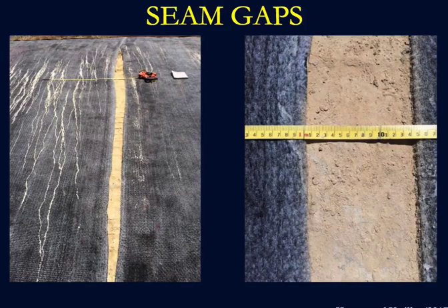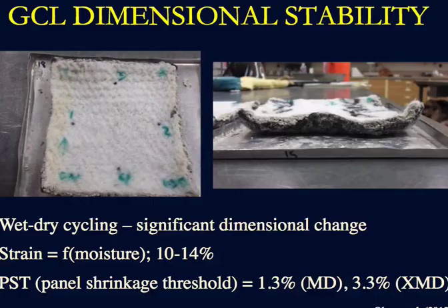And certainly here, the panel shrinkage has overcome that amount. And the close-up image in this case shows a gap width of 150 millimeters or 15 centimeters. We've done significant work in a laboratory setting related to quantifying this behavior, this panel shrinkage and dimensional stability through